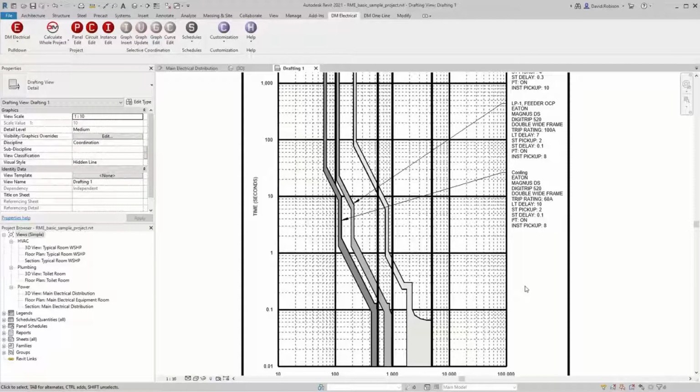So in general, work with the shared parameter file that's the lowest version of Revit that you're supporting in terms of your families and your projects. And know that anything that you do is going to be supported going forward in our software. Hopefully that answered all of your questions about shared parameters. We definitely don't want you to have to recreate stuff with every version of Revit. That workflow would not work for anybody. And so we are aware of that. So that is not the intention.